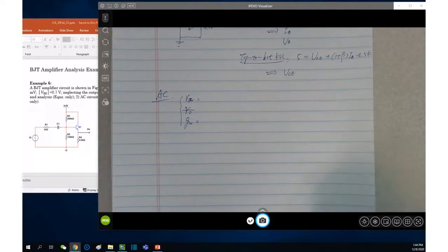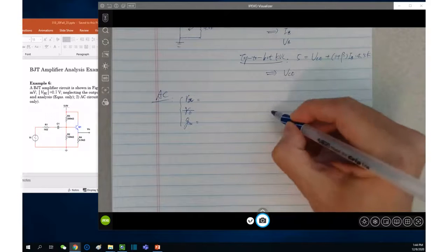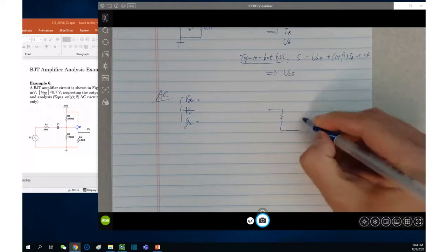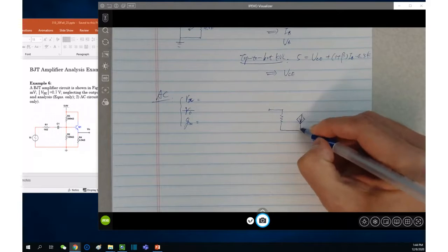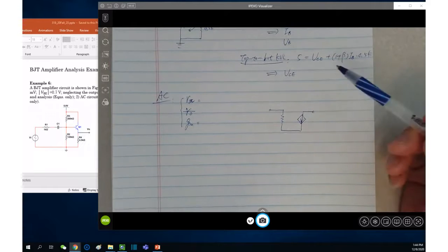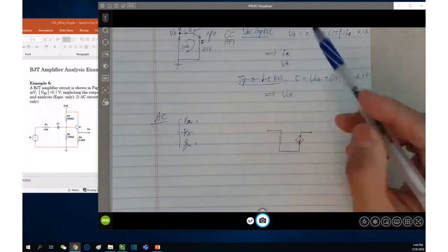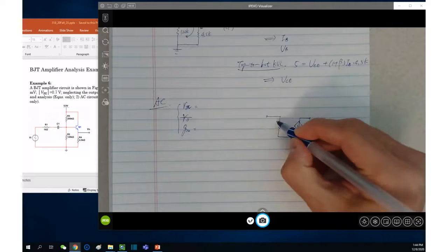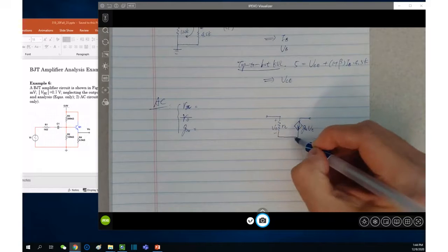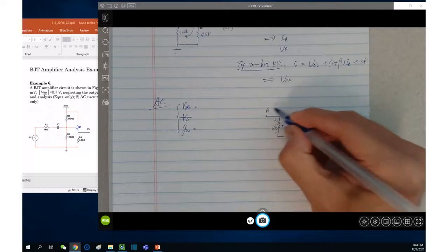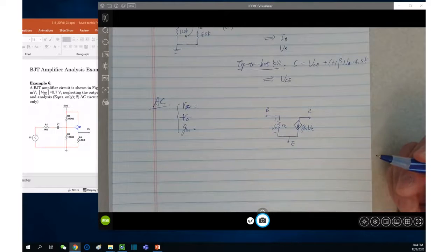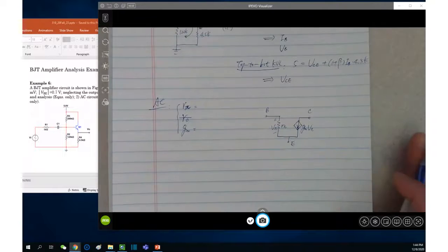All right, let's see the small signal circuit. Okay. Once again, we place the basic model right in the middle. And earlier we have identified this as NPN. So we are applying the NPN model. This is very important because if it is a PNP, you will have a different circuit. So this is the basic model, and then we're extending the circuit terminal by terminal.